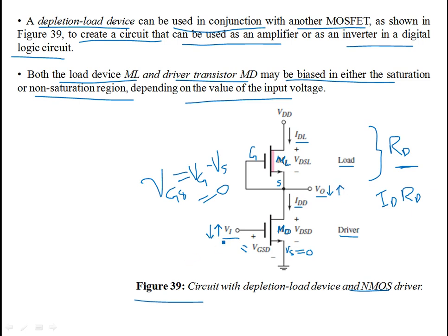So it's an inverter circuit, because if you decrease Vi, you tend to decrease the space charge density in the enhanced channel or the inversion layer. So the current reduces, the drop reduces, and the V0 increases. So it's an inverter circuit. Increasing Vi decreases V0, decreasing Vi increases V0. It's the same idea that we have discussed in the previous lectures.